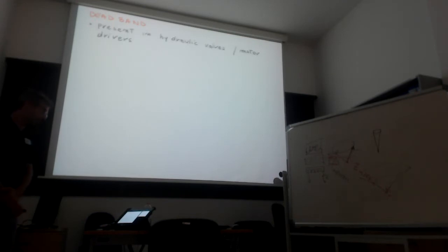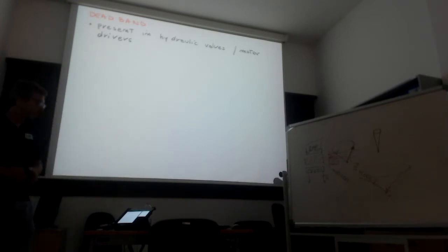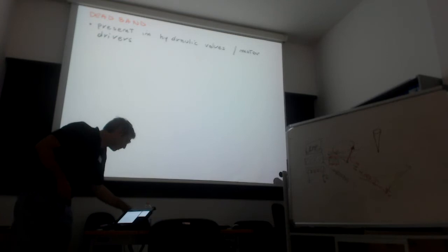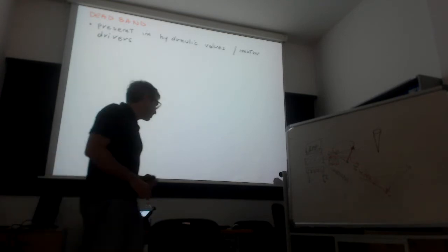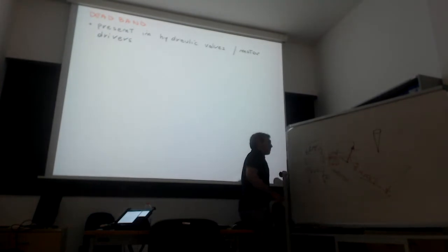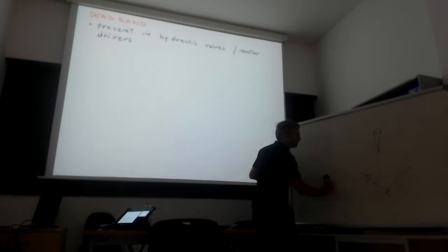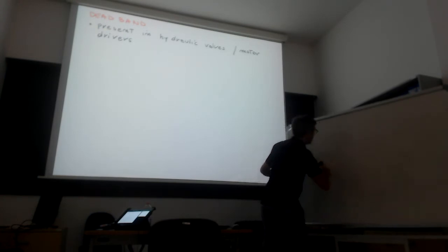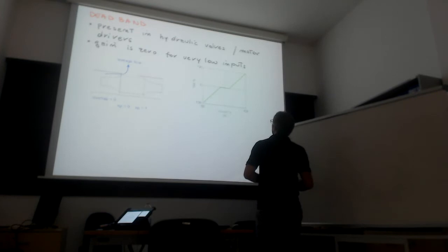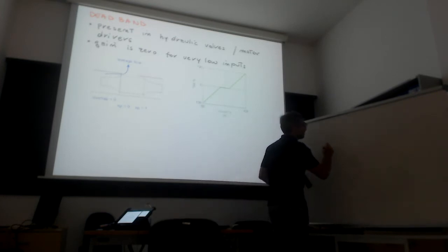Another point, especially whenever you have a hydraulic valve or motor driver, is the dead band. The dead band, in the case of a hydraulic valve, is whenever you have an overlap. So let's say you have the spool.